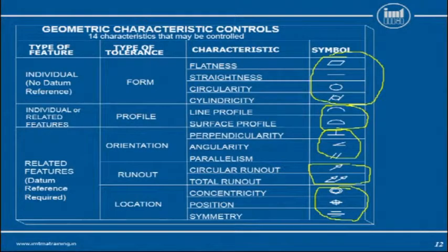The top surface needs to be parallel with the bottom surface within a given extent, say 0.5 millimeter or 0.1 millimeter, as the application demands. In other words, the parallelism control becomes a relative control and datums always need to be mentioned. So that is the chief difference between the form group of parameters and the remaining groups of parameters.